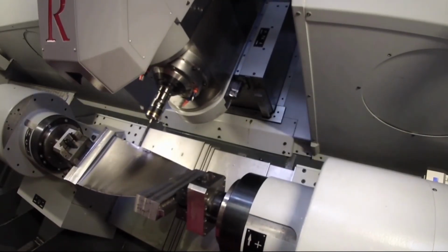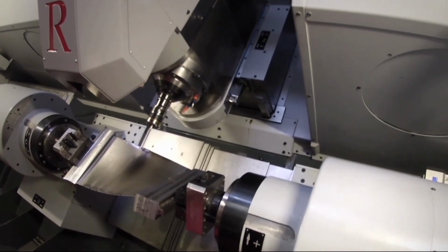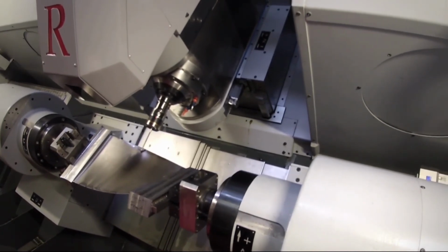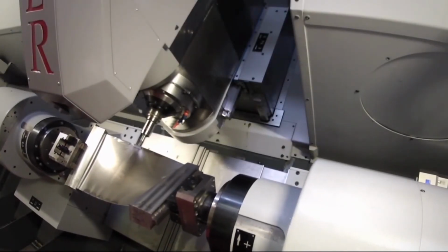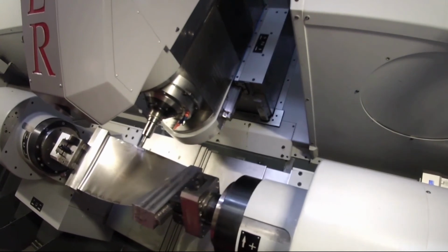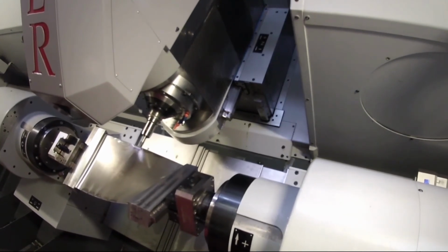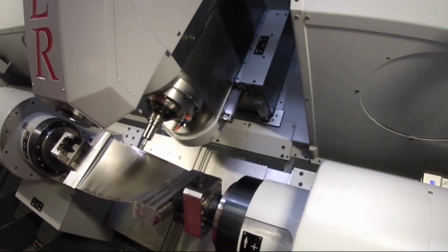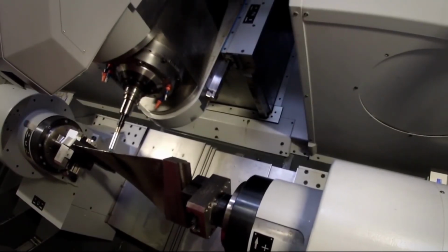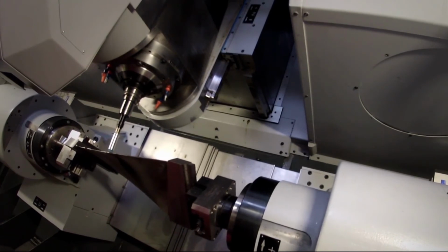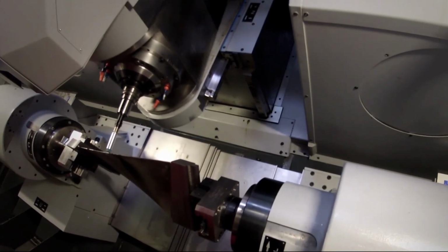We then bring in the inspection on the machine to be able to inspect the surfaces to make sure that we have actually truly added enough material to come back and finish. We then remachine this area. And finally, we have a polishing tool to be able to polish that edge up to the required surface finish.